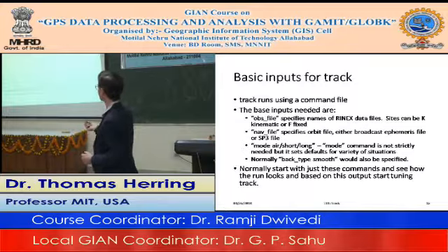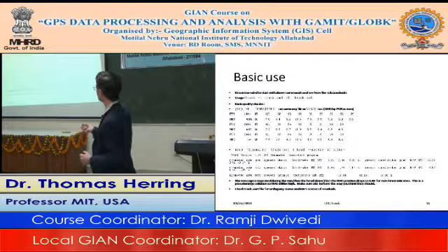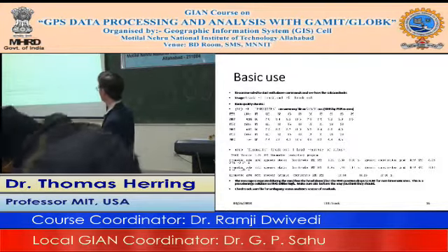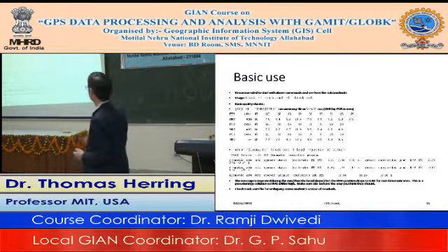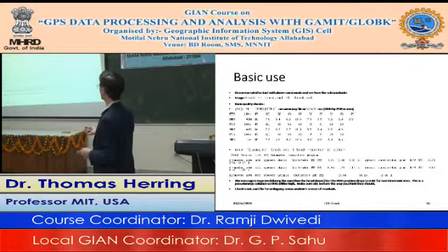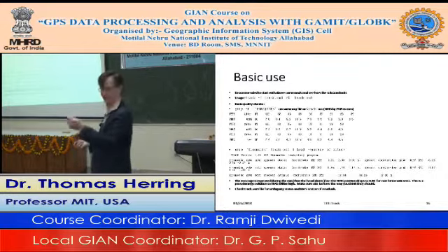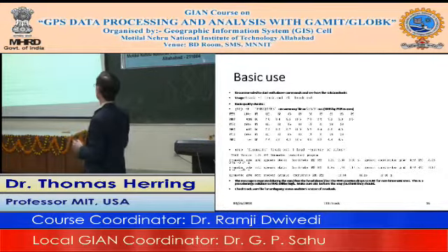So what's going to come out of this? Generally, when we run track, we pipe the output into an output file. Remember grep, which we really like to use. You look at two types of lines: the ones which have PRMS, which is phase RMS, and the other from the summary file that's written out, which by default would just be track.sum if you didn't give anything.